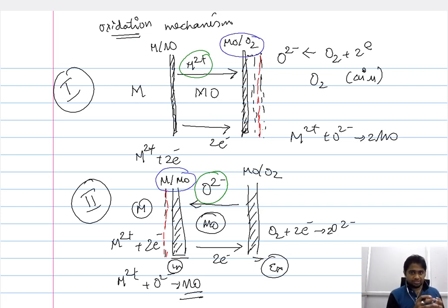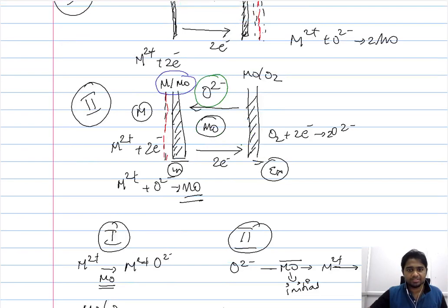So the temperature governs the oxidation in two ways. One is by controlling the kinetics of the propagation of these ions that principally govern the formation of metal oxide. The other is by causing the deterioration of the newly formed metal oxide, particularly in the case of mechanism 1, wherein the metal oxides are formed at the external interface. So by causing the deterioration, temperature can also influence the overall oxidation mechanism.